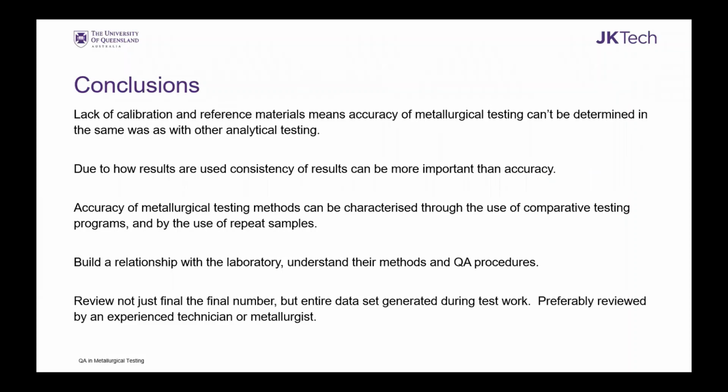Okay, so to sum up what we've done, metallurgical testing is a little different to normal analytical testing in that we can't use reference samples and we can't calibrate, which makes determining accuracy of results problematic.